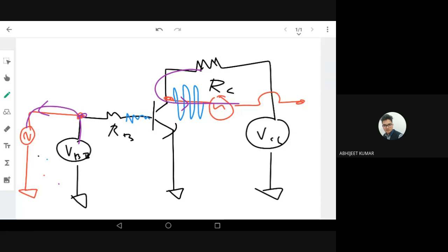You can try giving a buzzer. I think you know about a buzzer: if you give it a DC voltage, it vibrates. So the DC operating point can come into your input sensors, or it can also come to your output. So I need one device, one thing, which doesn't allow DC but allows AC.